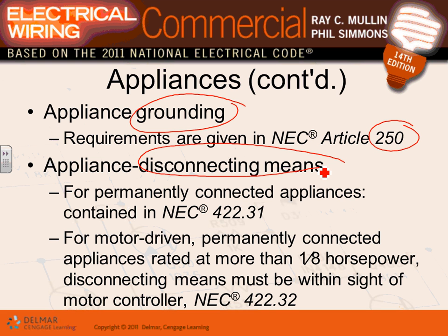Lockout, tag out procedures. When it's energized, you de-energize it, lock it, tag it, work on it safely, because believe it or not, we've had people lose fingers and hands inside these appliances. We've killed people inside these appliances. I know of a story where there was a kid who got inside a big mixer to clean it, and somebody started that mixer while the kid was there and completely cut him into little pieces. So you can imagine why disconnects are so important.